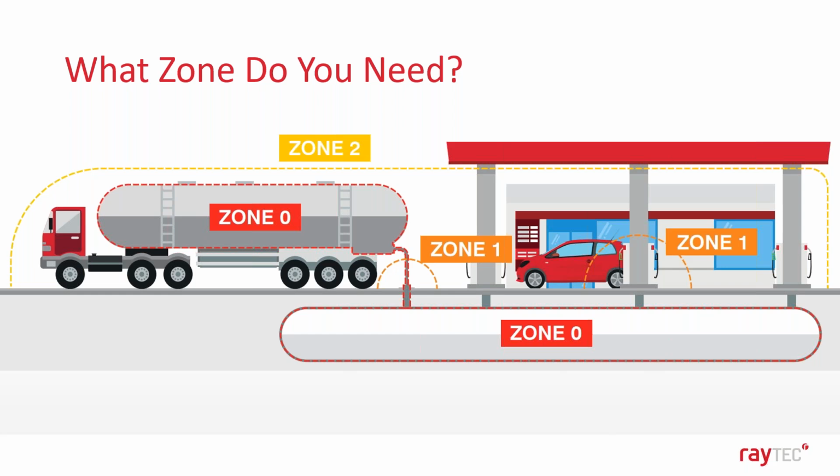But the level of protection provided by the equipment can vary, and therefore it's very important to make sure that you're using suitable luminaire for your application. This is by choosing your fitting based on suitability for the zone in which it will be located.